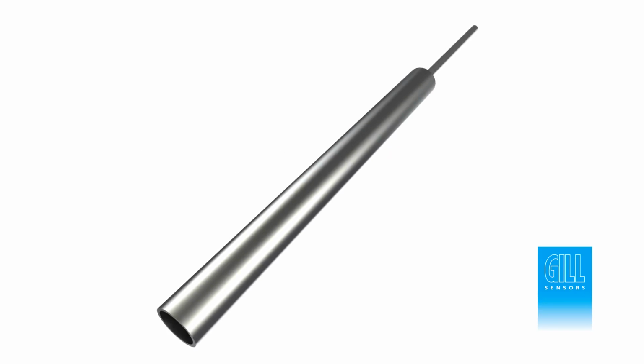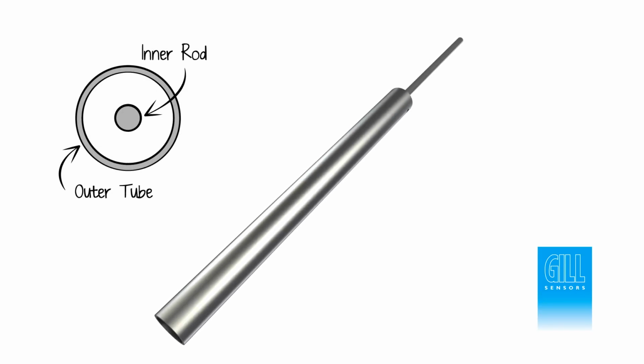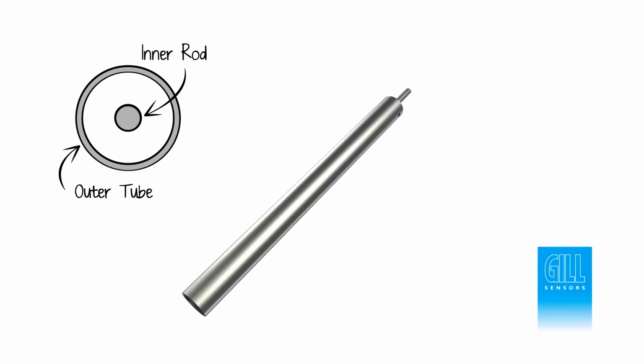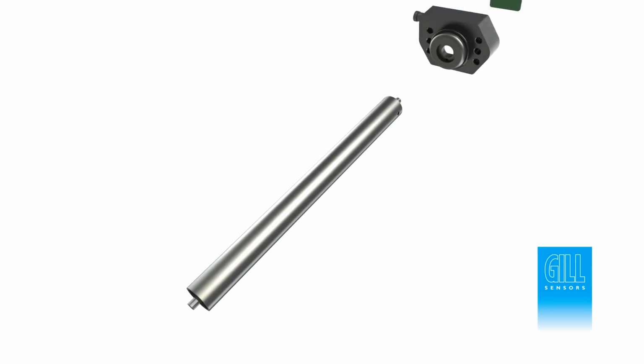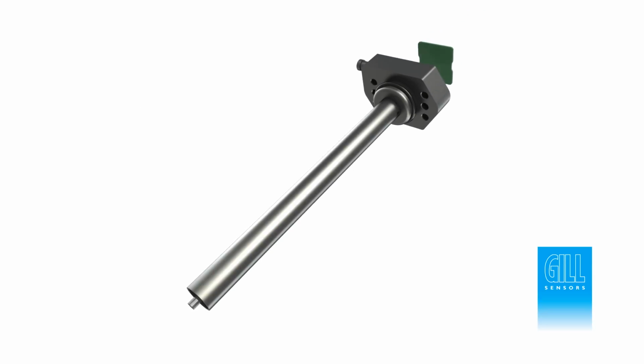Capacitor plates can also be deployed as concentric tubes, with the advantage of reduced interference, as well as improvements in mechanical stiffness and robustness. Fully integrated electronics mean no external electronic units are required, as all signal processing is managed on board.